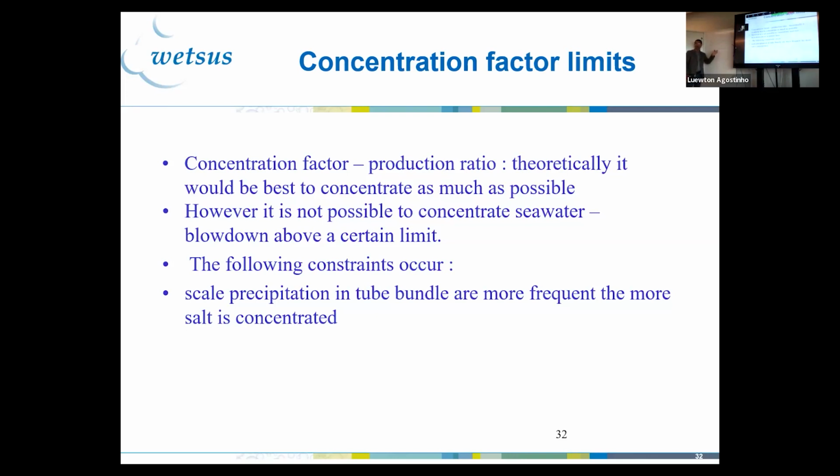And then very easily, you can make your calculations as well. If you remember the concentration saturation curve, you will see very quickly that you can reach saturation here. And if you reach saturation here, what happens in your system when you try to put the water back to the sea? Precipitation of the salt in your pipeline, precipitation of the salt in the system, and then very soon you're going to have to change all your pipes.